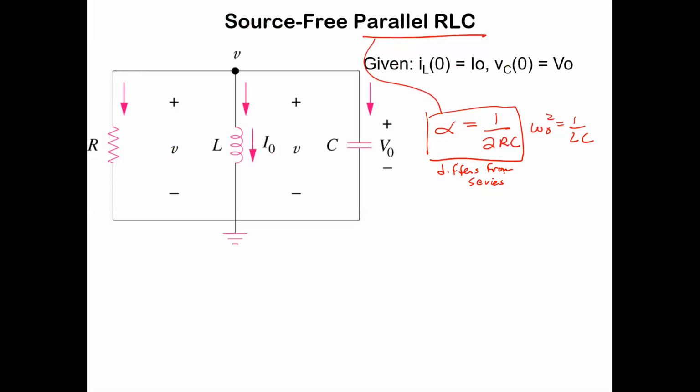And so when the current is 0, the inductor doesn't have any energy, but the capacitor may have all the energy in it. And then as it evolves, maybe the inductor current has the energy and the capacitor goes to 0. Now it doesn't have any energy, right? So they're actually exchanging energy between each other. What's the difference between a capacitor and an inductor? How they store energy. Capacitor stores it as voltage, as charge. Inductor stores it as flux in the magnetic field.